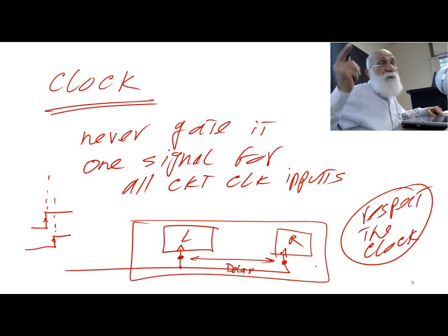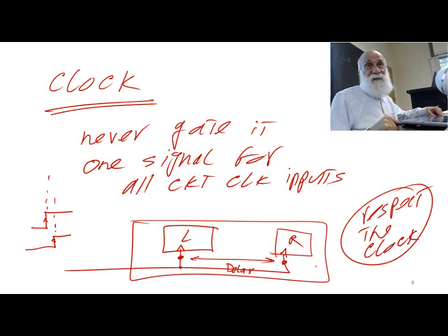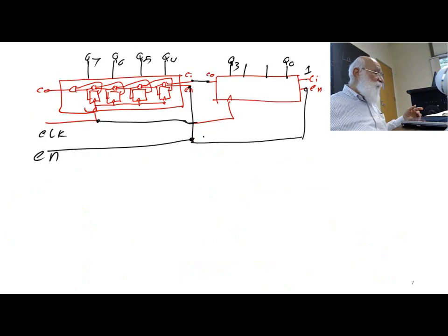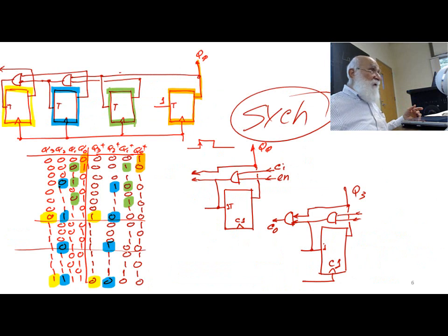When we are doing a clocked circuit, we don't play with the clock, and we don't let the clock participate in the designs either. What it means is that when I want to do a counter like this one, for example, I bring the clock, connect it to all my flip-flops, and say, now, let's start from now. Let's start from this point on.